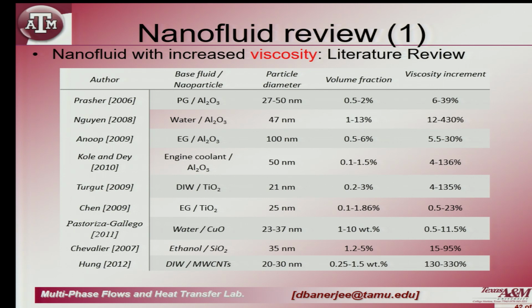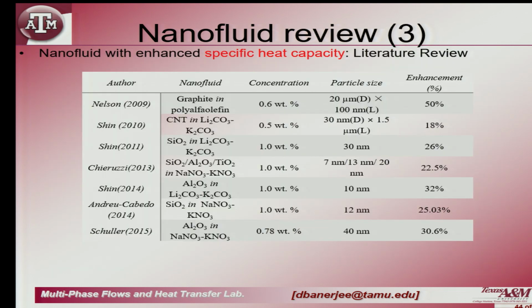But our research group was the first to show that the heat capacity also goes up. And then the misconception in the literature was that the heat capacity should go down, and same thing with the boiling experiments also. All those film boiling data that I showed you, our group has been the first and the only one that has done boiling on carbon nanotubes and silicon nanotubes, going from nucleate boiling all the way to film boiling, and also for big heaters. Our heater size was 5 centimeters by 3 centimeters, and 90% of the papers that you see in the literature these days are on 1 centimeter by 1 centimeter heaters with nano coatings on them.